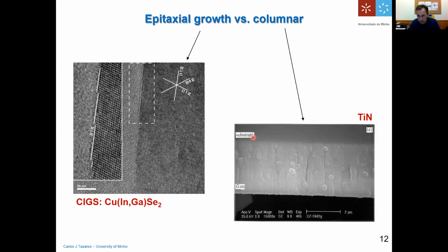So sometimes it's preferable, for example, if this is your substrate, imagine steel, it's better not to make the deposition of titanium nitride right away. So you should make, for example, an accommodation layer or interfacial layer, for example, of only titanium or chromium, that will serve as an adhesion layer, or a buffer layer, between the titanium nitride and your substrate.